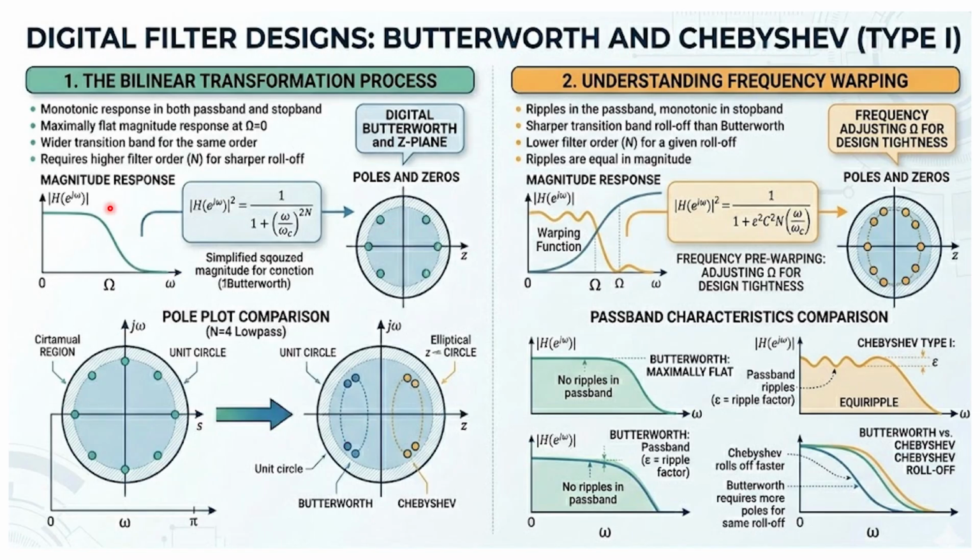And also you have to warp these frequencies in the z plane. So how will you warp the frequency to the z plane? We have already seen in the previous session that all the values of the s plane will map into the z plane, inside the unit circle, right?